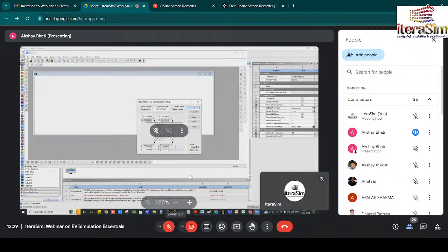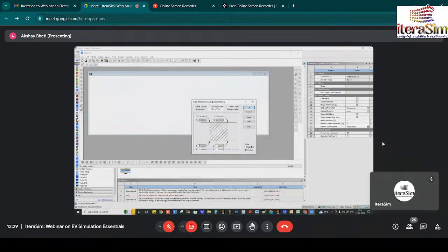In the direction of the fan, we are designing a small fan so that we can mesh easily. The fan length is 28 mm, the fan hub radius is 12 mm, the fan tip radius at the leading edge is 40 mm, and at the trailing edge is 80 mm. You can get these values depending on the requirement. If you have a space constraint, you want to develop a fan which should have the dimension like that,